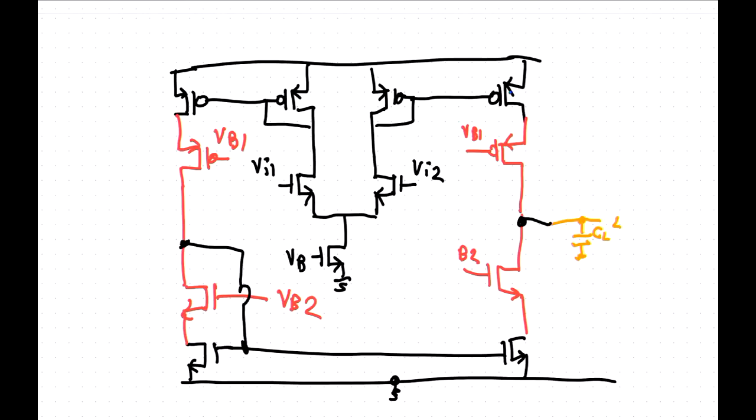Now, how do you do a fully differential op amp? Probably the easiest thing is to start with this circuit here and make one change. All you need to do is delete that wire there. Now it's fully differential. Oh, that was easy, wasn't it? So now we have two outputs, another output over here.